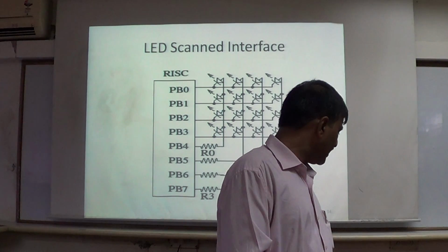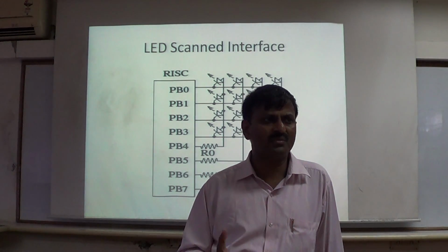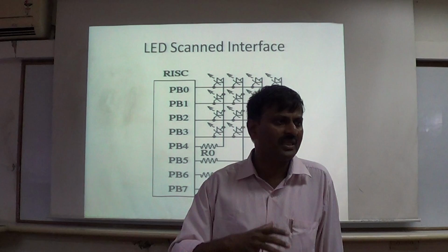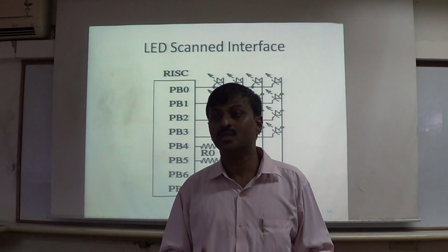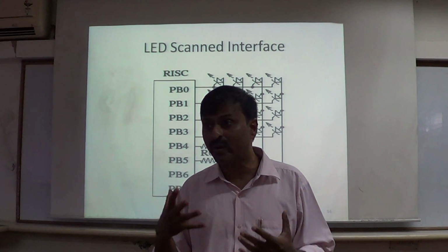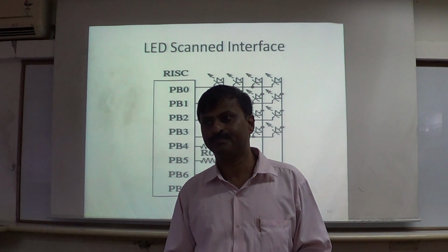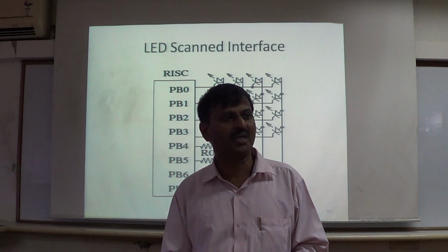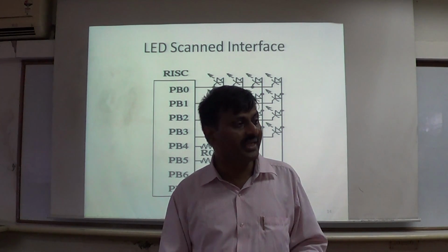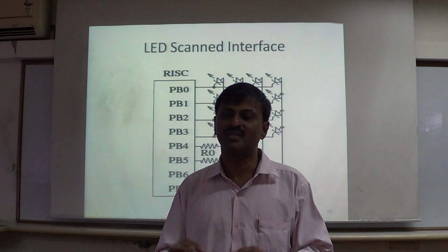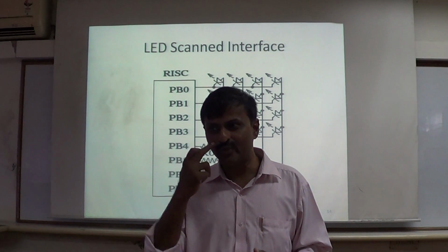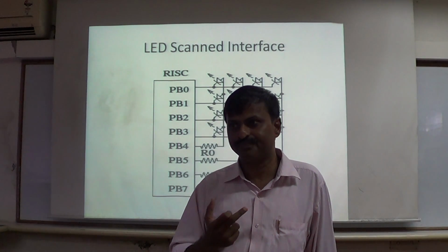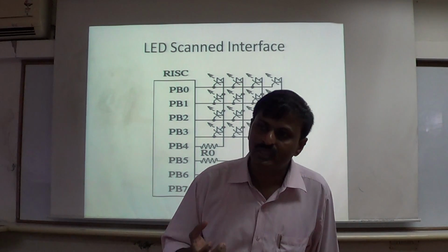So you talk about any motors, whether it's stepper motors or DC motors, servo motors, or even when it comes to human interface like switches and LEDs, these things cannot be done in micro or nano, though your microcontroller can send the data through I/O ports in micro or nanoseconds. In the case of motors, they are made up of inductors, right? And as far as LEDs are concerned, though it is a semiconductor device, if it switches very fast, the eye cannot sense. That's why we do not want that LED to switch in micro or nano, because of the persistence of the eye. Okay, so it is perfectly okay.